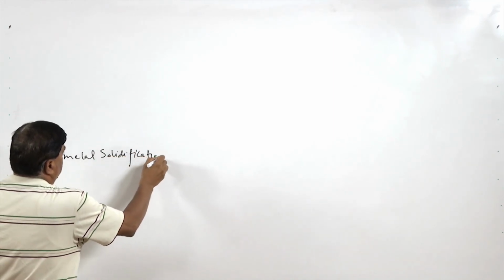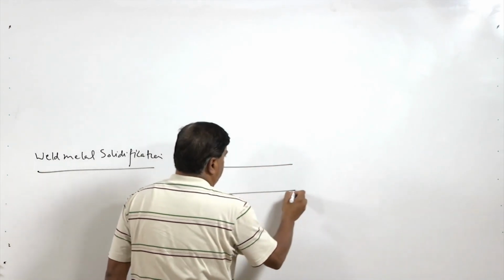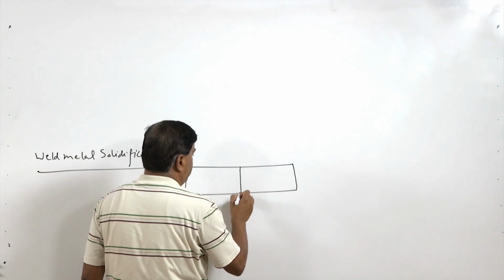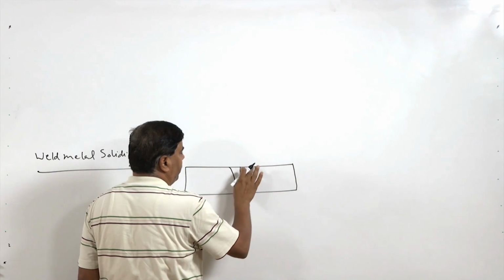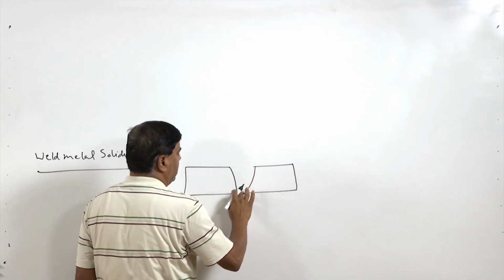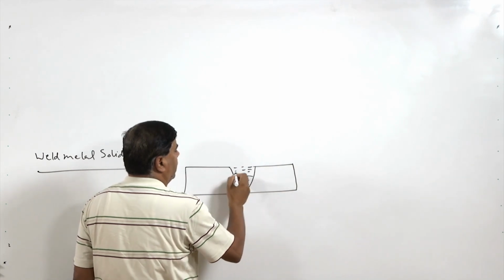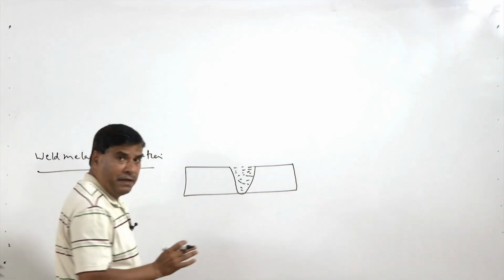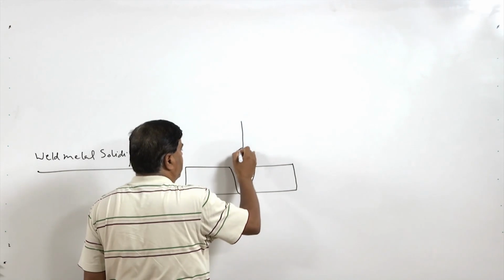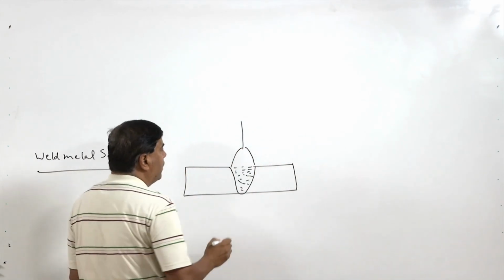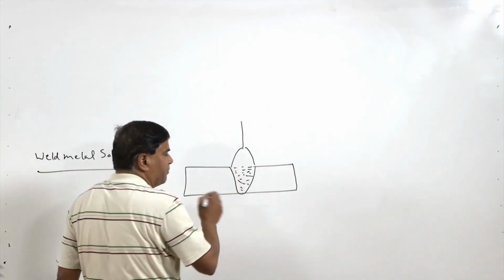We know that in fusion welding processes, when the base metal is joined, the fusion of the edges of the plate is achieved. So, the molten metal, the weld metal, may be either composed of just the base metal, or the filler metal may also be coming from the electrode or additionally from the outside.